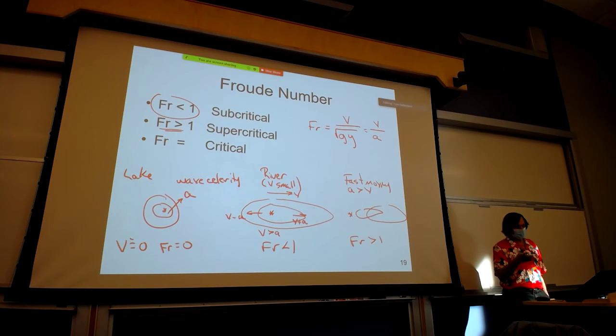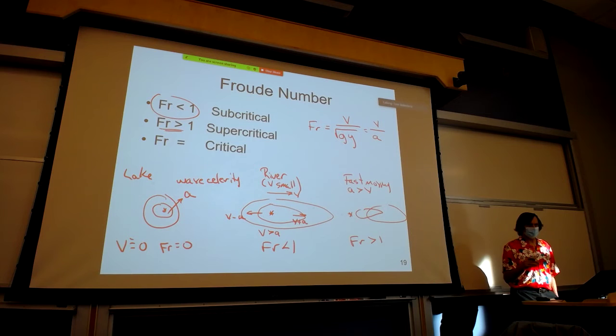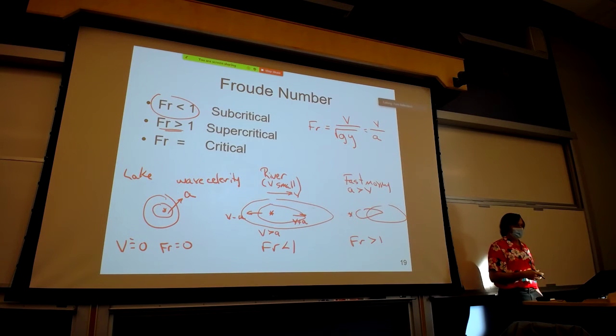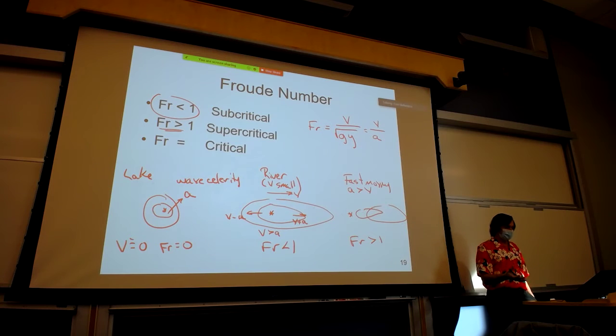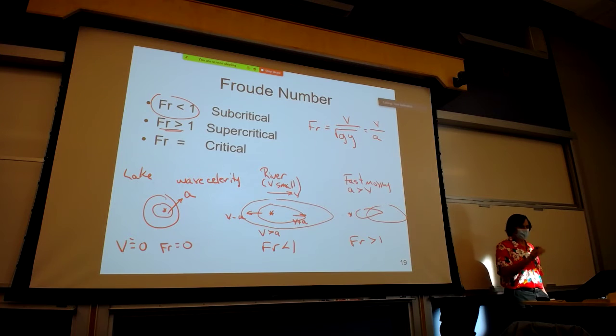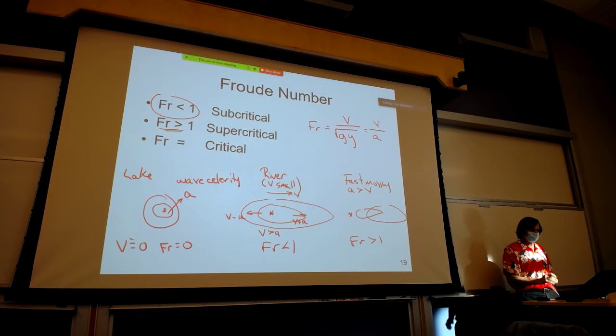How you perform the calculations when the Froude number is less than 1 is you start downstream and you make your calculations going upstream. In fast-moving streams, for supercritical flow, we have to go from upstream to downstream. So this has an effect, also obviously with the velocity, this has a significant effect on how sediment moves, how sediment bed features form in rivers, and a lot of other things. But we need to distinguish whether we have subcritical or supercritical flow in many of the open channel applications.